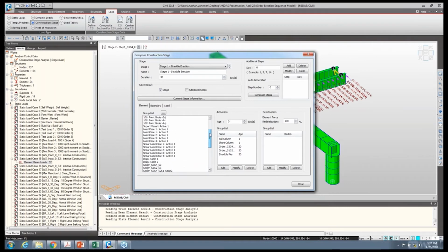So I'm going to go to my final girder erection, and I'm going to go to my results. And because, as I previously stated, in Florida, we have to tabulate all of our reactions due to wind and dead load during construction, MIDAS makes this process very simple by selecting certain stages. We can go ahead and select all of my stages through analysis. And as you'll see here, for each node, it's going to give me the respective results for each node and each construction stage.